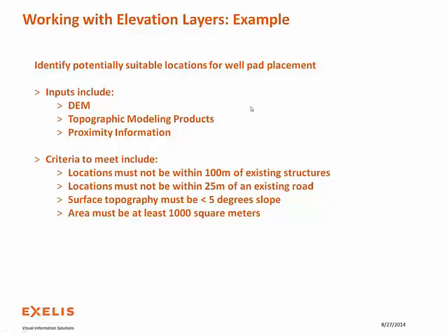So I've got a LiDAR point cloud from which I'm going to derive a digital elevation model. I have generated some topographic modeling products, which we'll look at, from that DEM, and some proximity information because I've got these criteria to meet where these sites that I might place must not be within 100 meters of existing structures, the buildings. The locations must not be on or within 25 meters of an existing road.